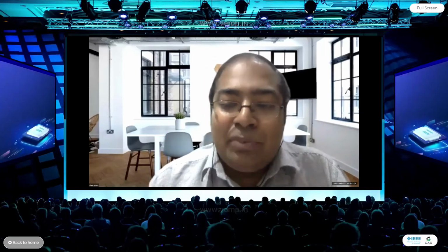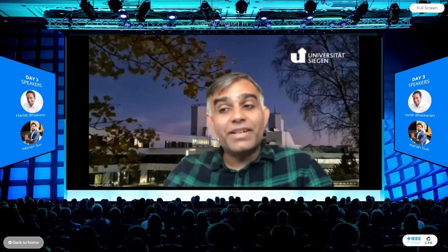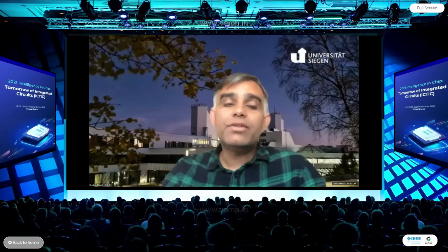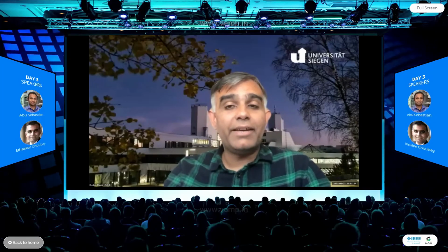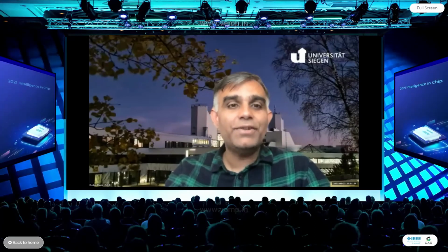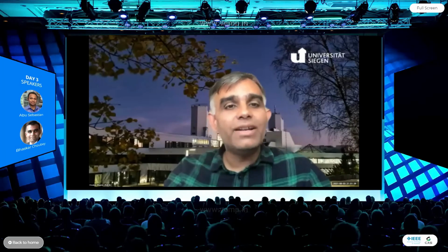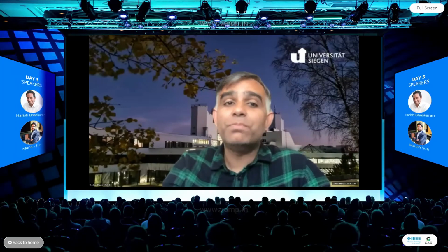Yeah, another question: what are the challenges if we are to implement a neural network on the same chip as the image sensor? Oh gosh, where to start? First is the imager. Either we're trying to make a neural network on the same chip, or we are trying to make a neural network with the pixel. Neural networks themselves are fairly large, so we need to cut down the size of the neural network, and maybe be less ambitious about what it can do. Second, as we talked about, we also need to be less ambitious on the size of the pixel and the size of the image sensor. So we need to reduce the ambition in both domains and then design a system together.